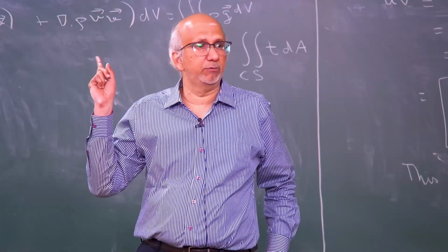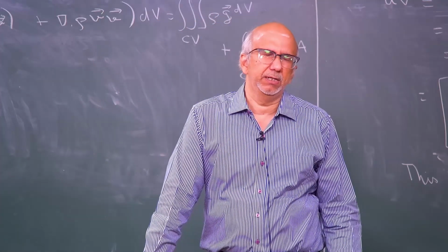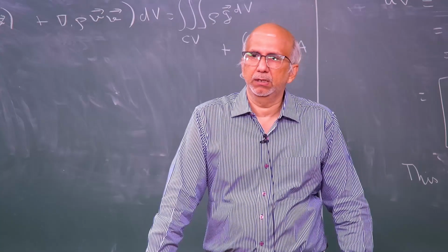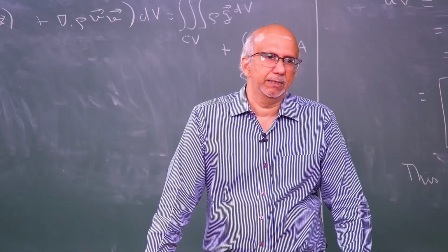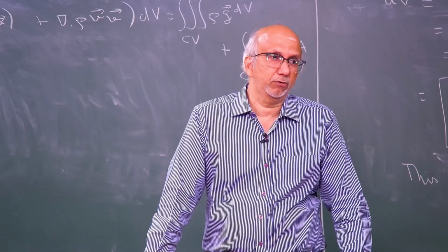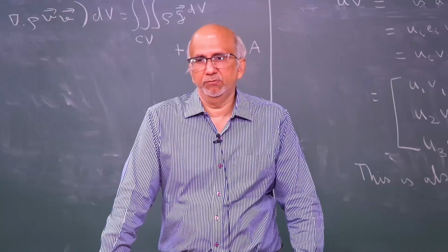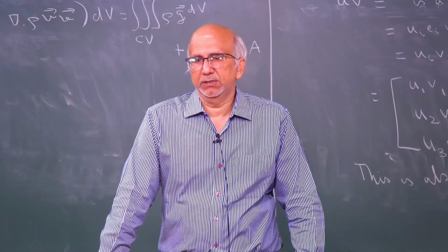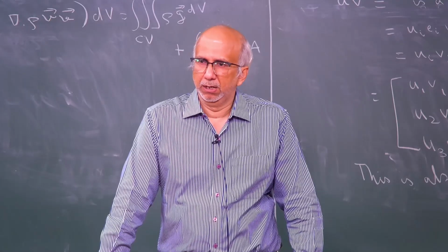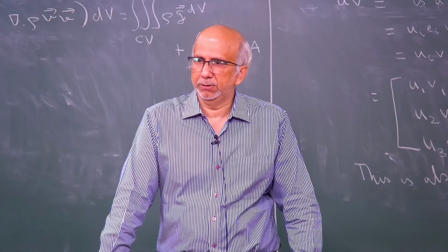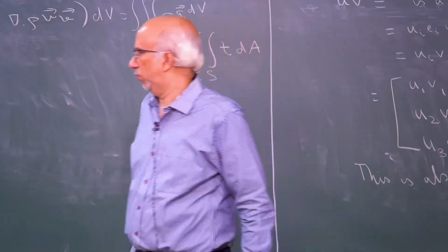That is what we did, if you remember, when I did the divergence, the equation of continuity. I said it is valid for any arbitrary control volume, and then I derived the equation of continuity from Reynolds transport theorem. From Reynolds transport theorem, we converted the surface integral to a volume integral, and then wrote the equation of continuity. So, same thing we want to do here. I want to do it for as small a control volume as possible.